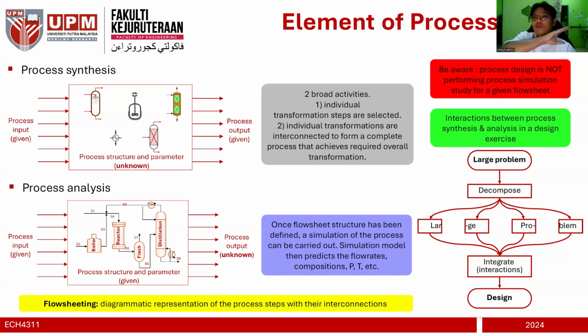Your raw material is polymer grade ethylene or polymer grade propylene. When you have polymer grade, it's around 99.5% ethylene and 0.5% ethane, or 0.5% propane, and it goes into the reactors. They know all of the process, but over time there's going to be a buildup of propane. So what they do is they flare the unreacted propane and unreacted ethane.